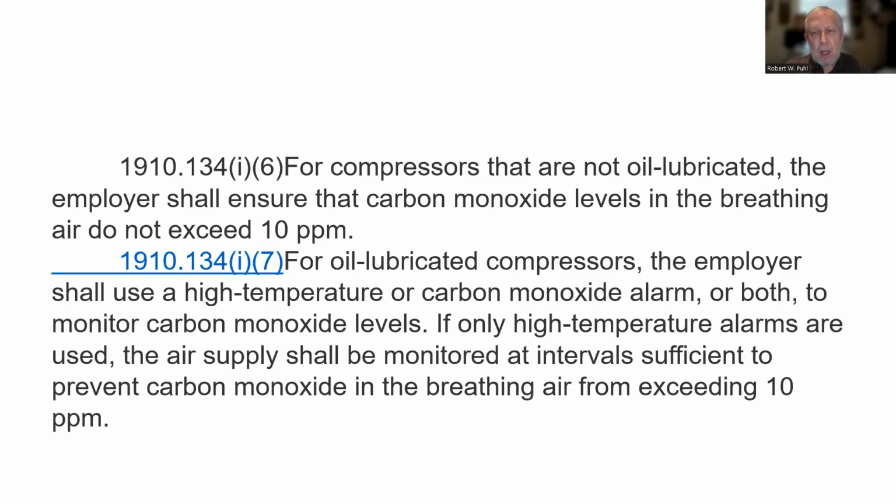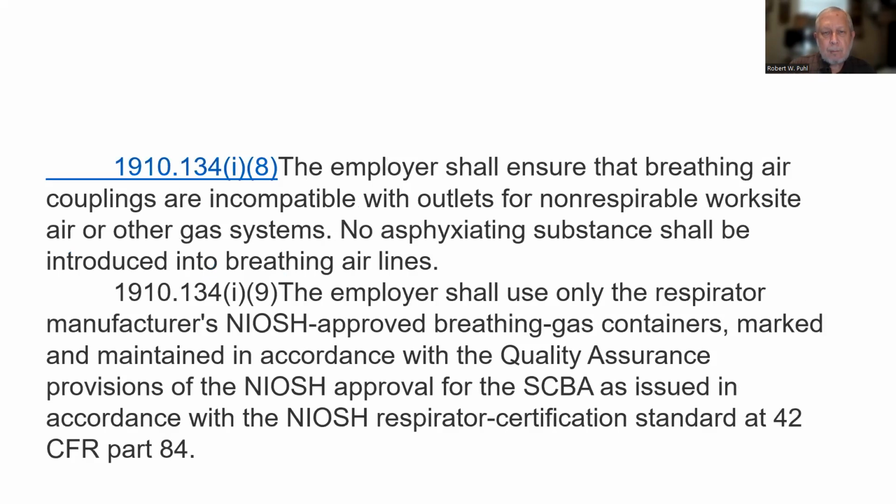For compressors that are not oil lubricated, the employer shall ensure that carbon monoxide levels in the breathing air do not exceed 10 parts per million. For oil lubricated compressors, the employer shall use a high temperature or carbon monoxide alarm or both to monitor carbon monoxide levels. If only high temperature alarms are used, the air supply shall be monitored at intervals sufficient to prevent carbon monoxide in the breathing air from exceeding 10 parts per million.